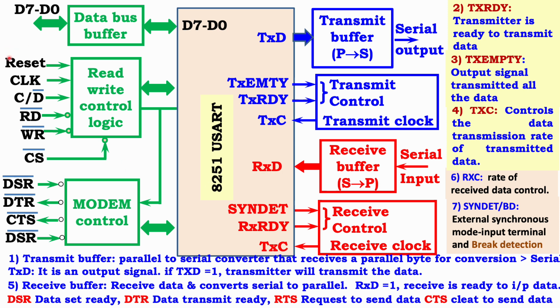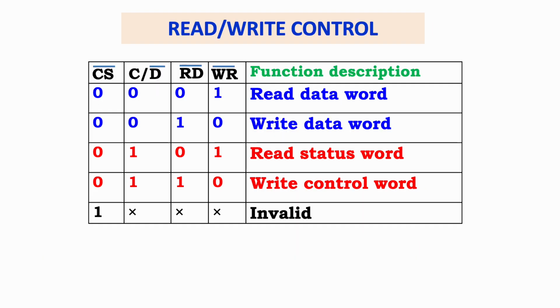And one more important block is the read-write block. Whenever we want to use the read-write operation, these signals are initialized properly, and the read-write logic control can be opened. Of course, we know that the data buffer carries bidirectional data between the processor and any peripheral device during data communication, and the entire operation is synchronous with the internal bus of the 8251. Now let us discuss how the read-write logic control does the read-write operation. How can we select it? With RD bar and WR bar.